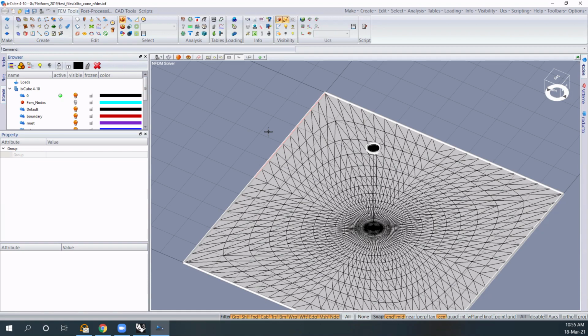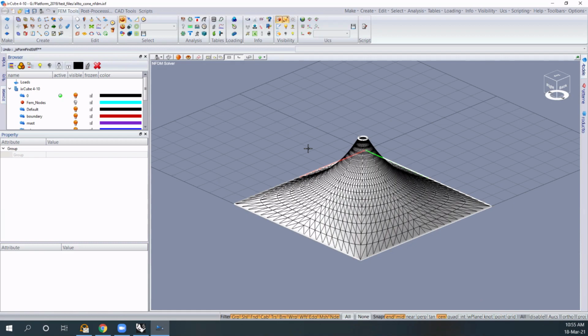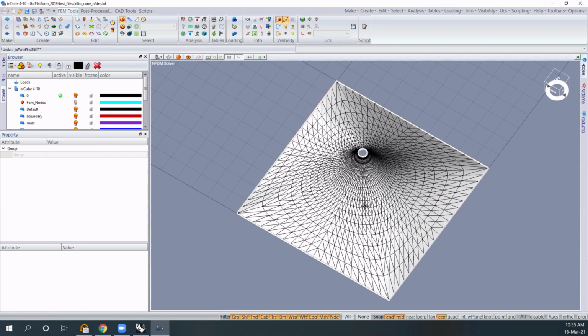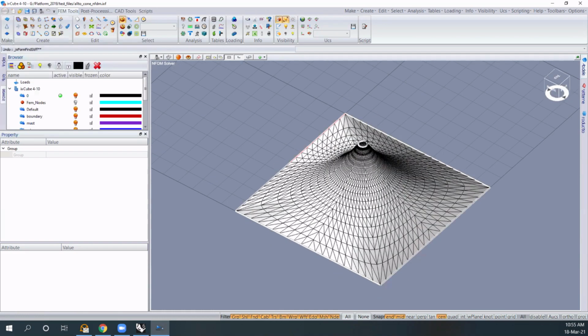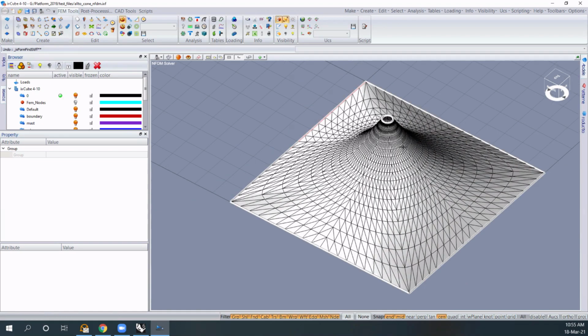You say, okay, but how do I, if I want to use the, I will roll back. If I want to use the natural force density method, I want to find this shape. Well, if you want to find this shape, I will run again. We have to put inside this membrane some cables or some links that fix the problem that this membrane tends to collapse in the middle line.